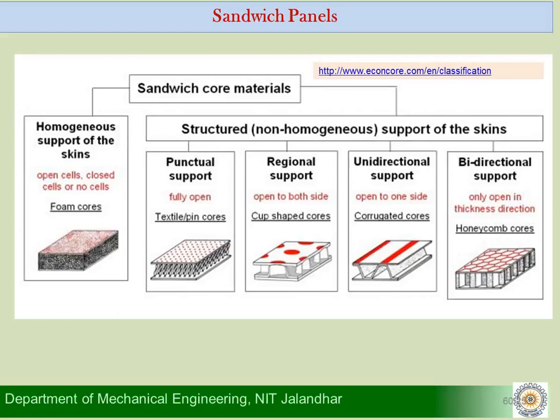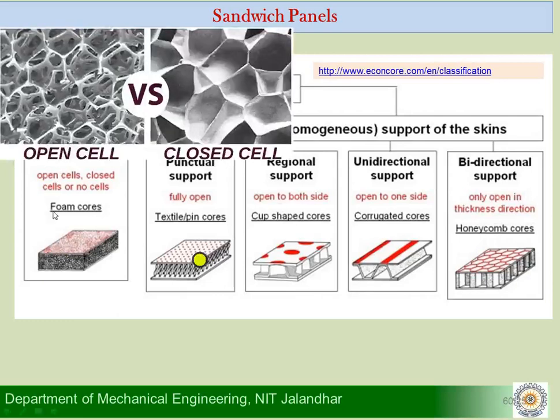What is meant by an open cell foam or a closed cell foam is shown here. So we understand how you create a foam. You take a solid material, maybe a polymer, and blow a gas or a blowing agent or air through it, which creates pores inside it. This gives rise to foamification, which reduces the relative density of the foam with respect to the density of the solid of which this foam is made.